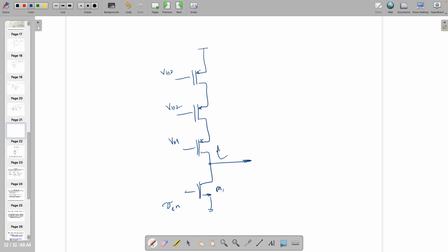What is the resistance looking upside? If it is M1, M2 and M3, this is GM1, RO1, GM2, RO2 and times RO3. If this is diode connected, then it's 1 by GM3. If it is a resistance, multiplied by resistance, right? These are very simple. This is the triple Cascade, by the way. If it is just like this, now tell me, what will be the gain?